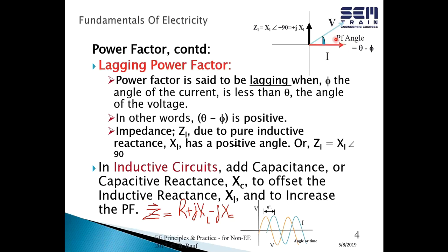So that's essentially what we're looking at. Current is lagging behind the voltage. If you view these vectors rotating counterclockwise, you will see voltage go by first and then current, and hence you say that the current is lagging behind the voltage. I'm explaining anecdotally, graphically, and physically this whole concept of power factor, with the hope that as you understand the physical aspects of power factor, you'll be able to analyze and understand any power factor question you encounter in the exam easily, and immerse yourself in the problem, see it, analyze it quickly, and solve it quickly.